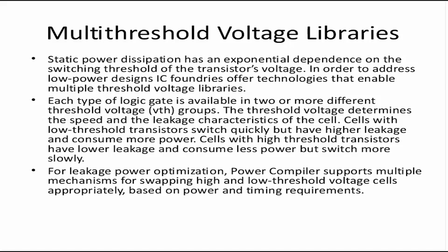So what many people do is say, okay, I'll only synthesize with high VT to achieve the best power number. I'll only synthesize with high VT, since the critical paths can change after synthesis, right? Synthesis does not have accurate net information because the design has not been placed and routed. Synthesis does not have the accurate net and capacitance numbers; accurate information is available only after placement and routing is done. So the critical paths can change after placement and routing.